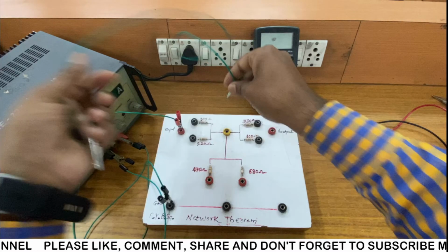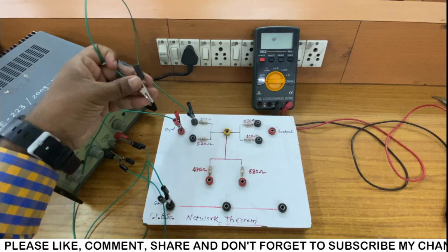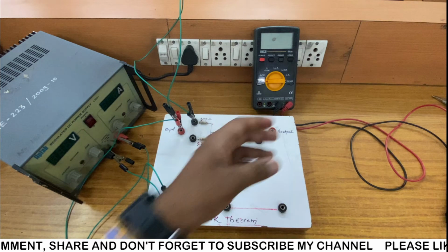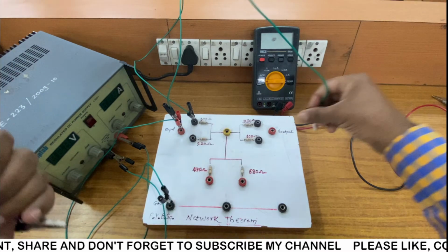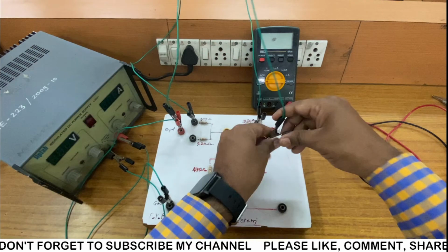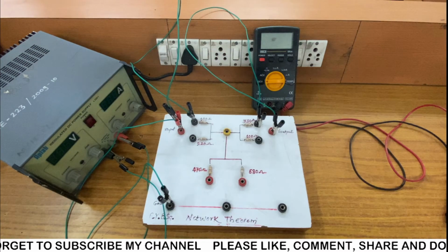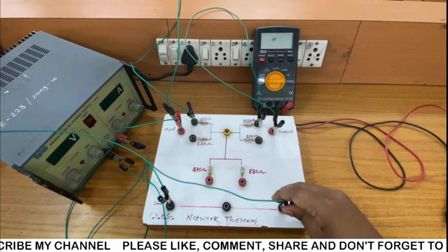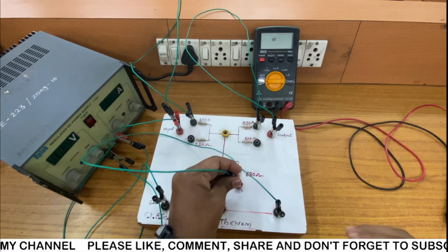So I'm going to connect the VCC 5 volt and ground. Then we need resistance R1 to be 100 ohm. Then the next resistance R2 is actually 330 ohm, connecting it to the output. The next is 680. Connect the 680 resistance to ground.